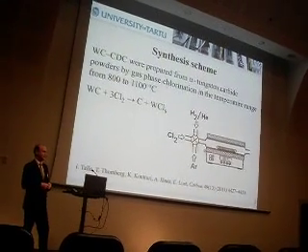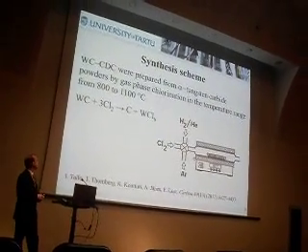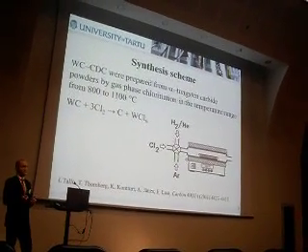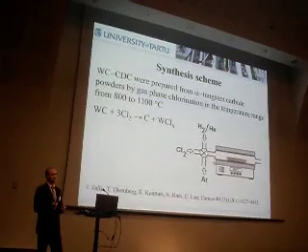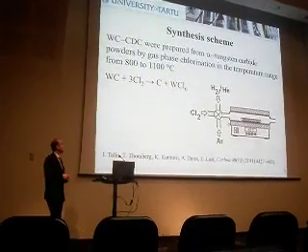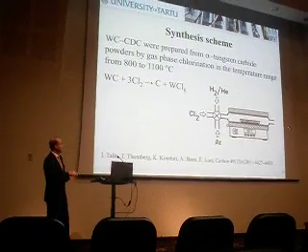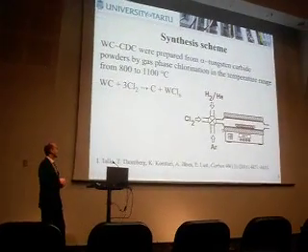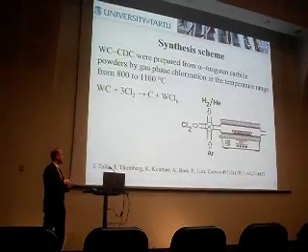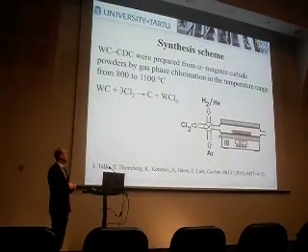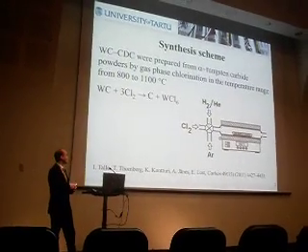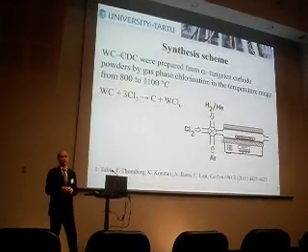And we used alpha tungsten carbide. The powder was particle size about 10 micrometers or less, and used this oven as a synthesis vessel. And the way the process works is that we heat it up in an inert atmosphere and flow chlorine gas through the system.